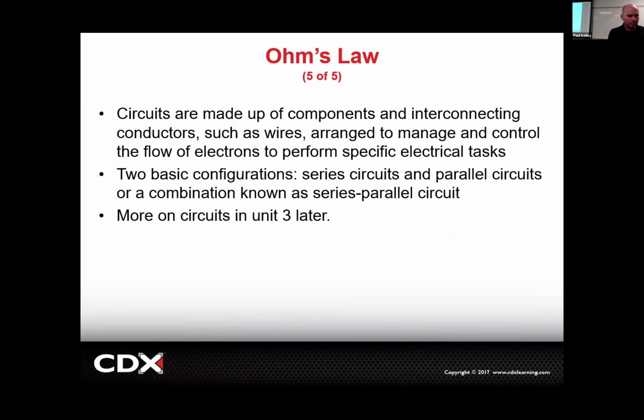And there's going to be several different types. Series, which is where we're mostly going to spend our time. And parallel. We're going to go into parallel, but I don't spend a ton of time on parallel, mainly because when you have a problem in a parallel circuit, the best way to troubleshoot it is to break it into multiple series circuits. So you have to know what to do to start, and then once you understand the parallel, you'd be like, all right, I'm just going to focus on this part of the circuit because I understand how it works, and then you're basically back to series.